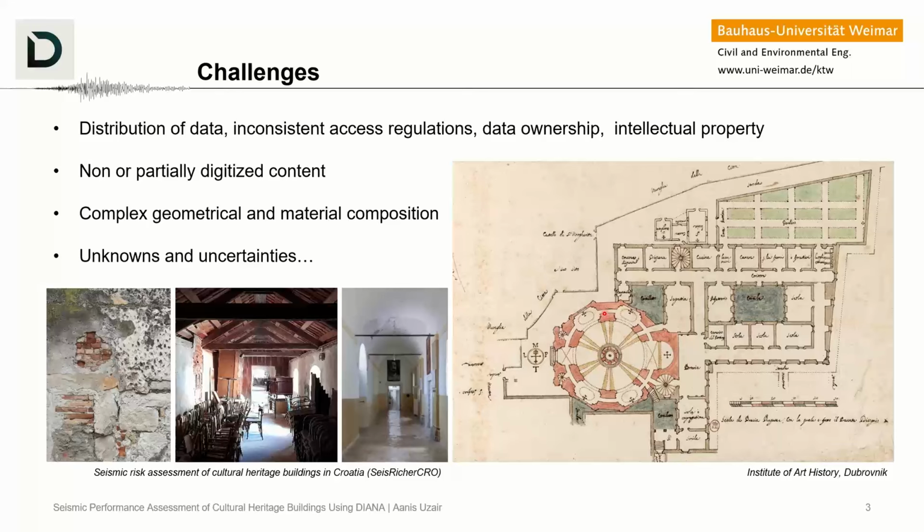And I will later show you why we exclude them in the numerical model in certain cases where we don't know anything about the connections. It's rather better to exclude them than to consider them and have a weaker structural response in a particular direction or stress concentration near the edges of the walls.